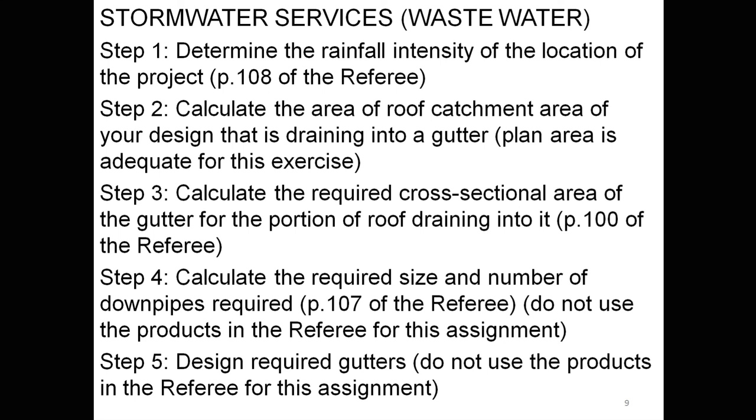Essentially, if you had a lot of rain, your overflow is not going to help you that much if your downpipe is completely blocked, because it will just back up and the whole thing will fill up, and the overflow won't be able to get rid of enough water to stop it backwashing into the house. So the domestic situation is different again. Generally, box gutters do hit the outside of the buildings, and then you have a rainwater head, which is a tank that collects all the water, and then it overflows.